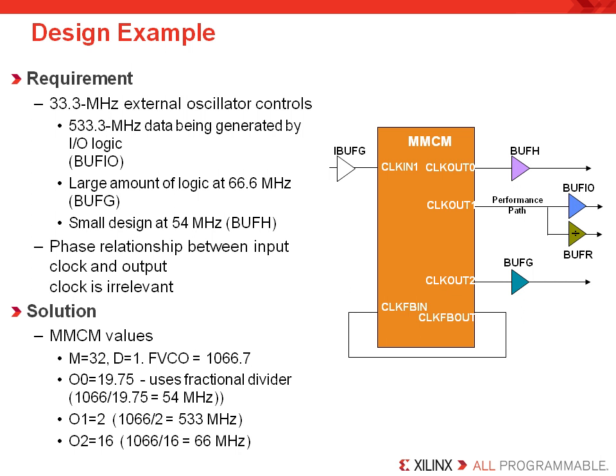Recall that you have a limit of 32 global clocks you can distribute on the BUFG resources. Finally, the highest fan-out clock simply divides the VCO by 16, a simple integer value, and that means it can be generated by any of the output ports on the MMCM.